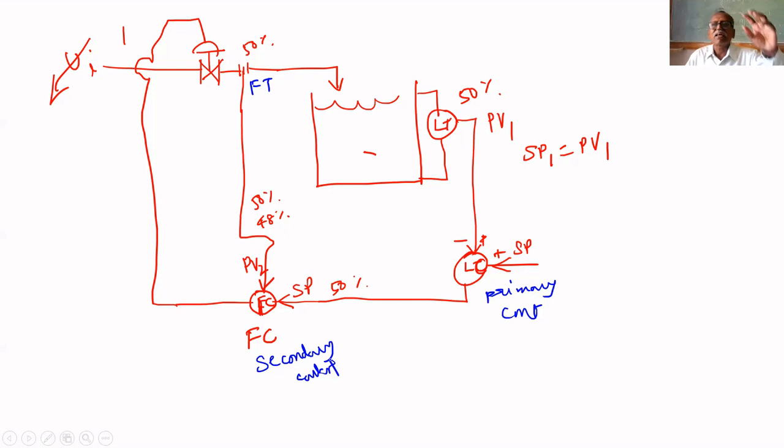That's why in an electronic PID controller, while configuring, you can give the set point from another process. Suppose you want to use cascade control, which means you have to use 2 PID controllers. For level, you will use 1 PID controller, as we have seen, and we give the set point there. Here, the secondary controller's set point is given by the primary controller. So here also, the set point will be 4 to 20 milliamps, given as the set point to that.